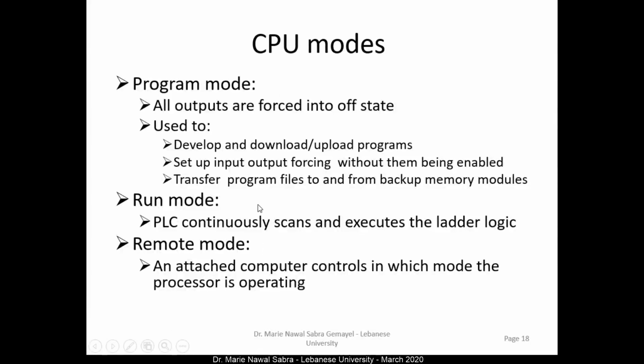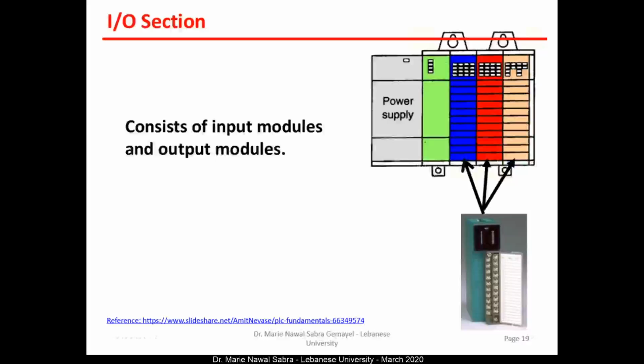The run mode is when the PLC is running normally. The remote mode is if the PLC is attached to a different PLC or to a computer, and the computer is controlling the PLC. This is what we call a remote mode.